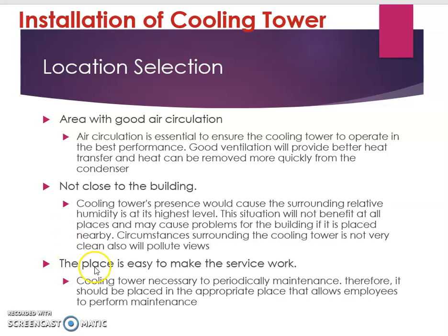The next thing we have to look into is that our cooling tower must not be close to the building. Usually they will put a cooling tower on the rooftop because it is not close to the building windows, for example. If the location of the cooling tower and the building windows, doors is near, it will give a bad impression, for example. So not clean.